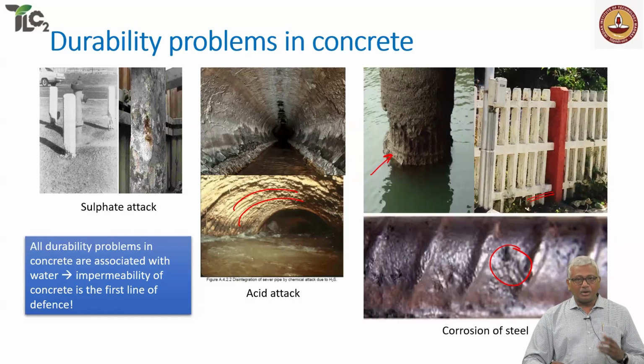Okay, so all these durability problems are very clearly associated with the presence of water, right? Water is either needed for the reactions to happen, or water is needed for the reaction to propagate. Without water, none of these durability problems will actually affect concrete. In other words, you need some moisture to carry forward these problems. If you keep your concrete dry and free from moisture, many of these problems will cease to exist. You'll really not have any issues as far as long-term performance is concerned, but we know that's not going to happen. During its lifetime, concrete will get re-wetted multiple times.